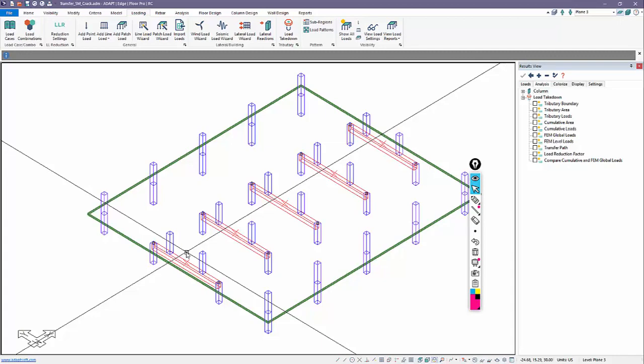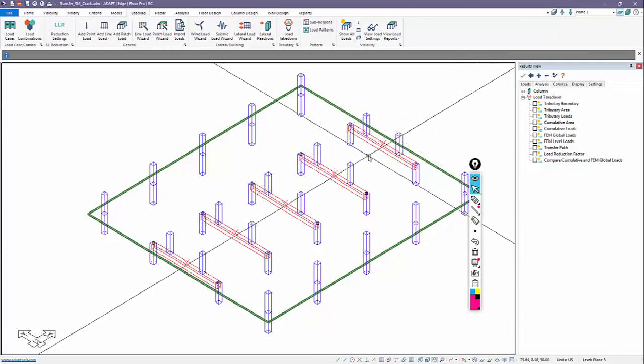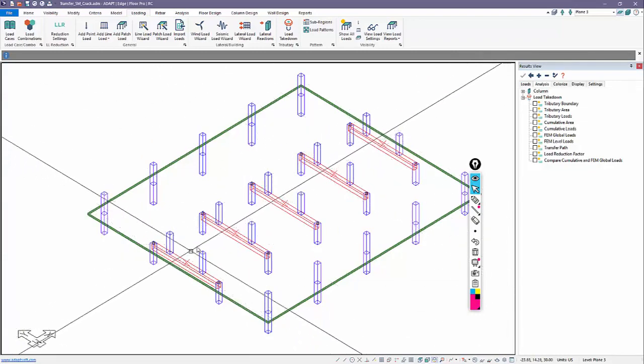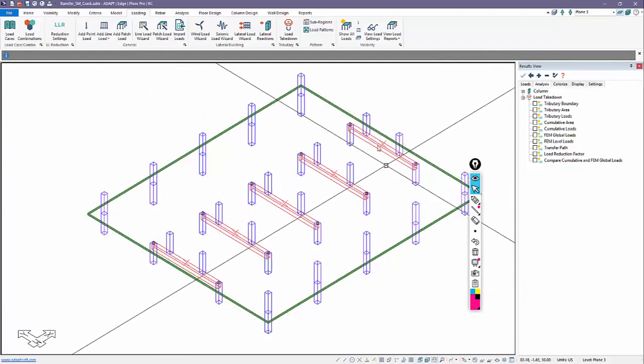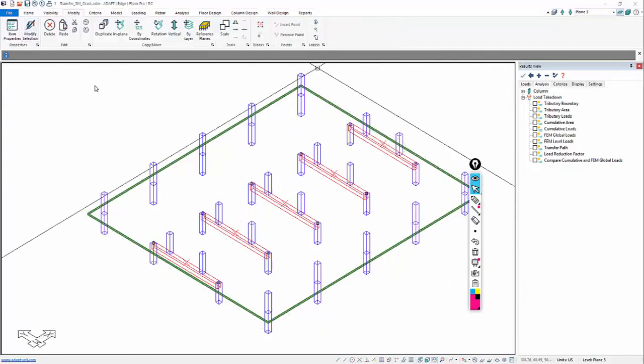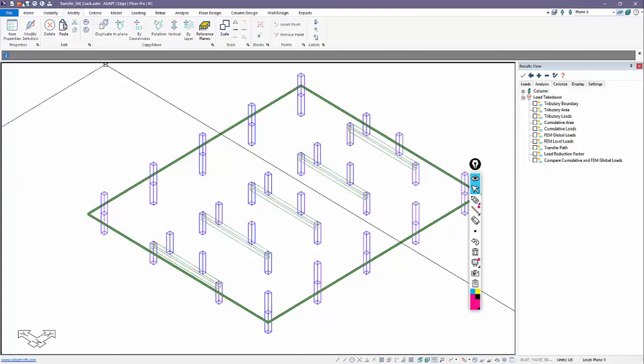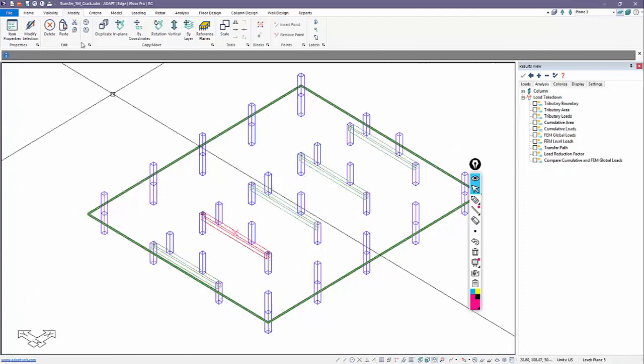So we'll apply a modifier of 0.35 to this beam for flexure, just as the example. After I set up the usage case, I'll select the beams, I'll use modify selection, and for beam we're going to go to stiffness and we're going to change this to 0.35. Okay, and that changes those modifiers.